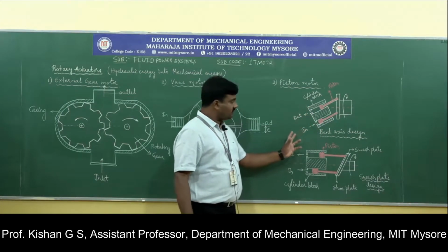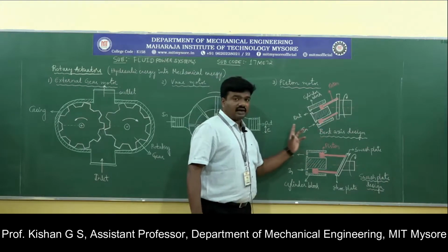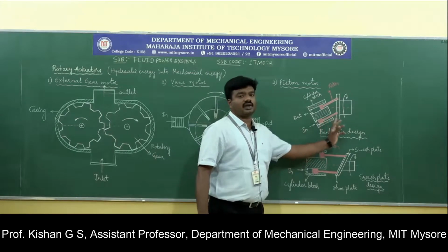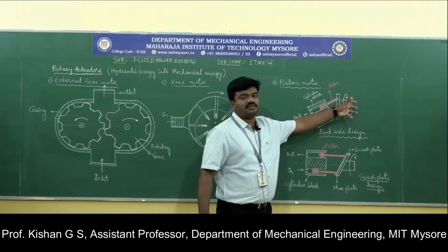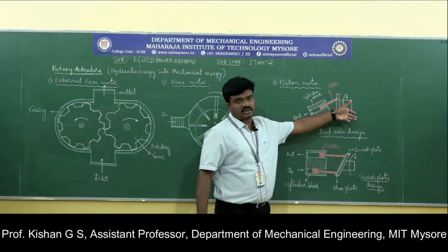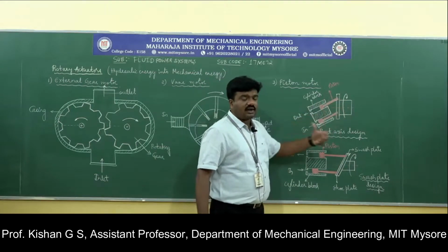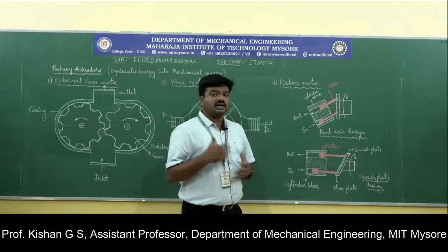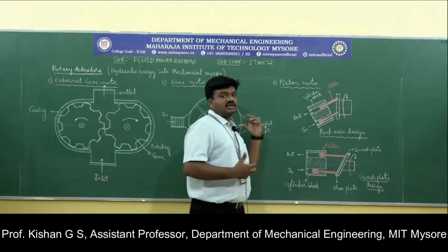When there is a flow of high pressurized fluid into the inlet, that results in the extension of piston from one end to another end, that leads to the transfer of rotation to the shaft which is connected to the system here. Similarly, once it rotates, that hydraulic energy or pressurized fluid that has resulted in the rotation of the shaft will be taken out of the system.